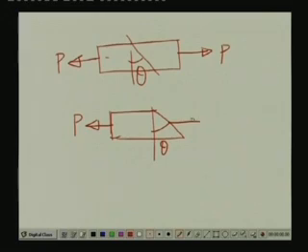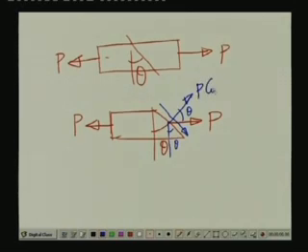The resistive force acting on this body to keep it in equilibrium is P. So, this will have two components, one along the normal and one along the plane of this particular section. Now, this angle being theta, if we drop a perpendicular here, this angle also is theta, hence this particular angle also is theta. So, the force component along this is P cos theta, and the force component along this is P sin theta.